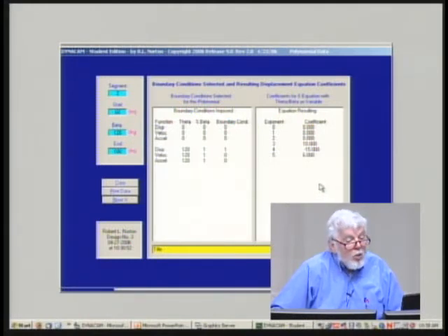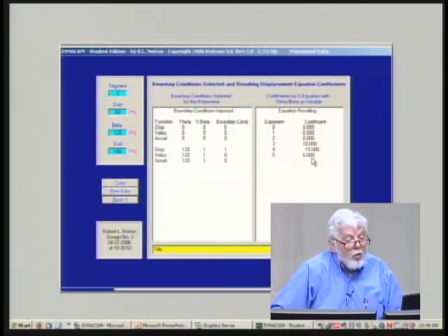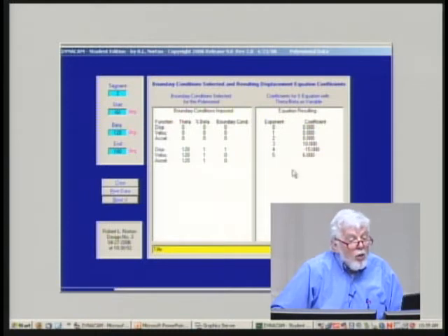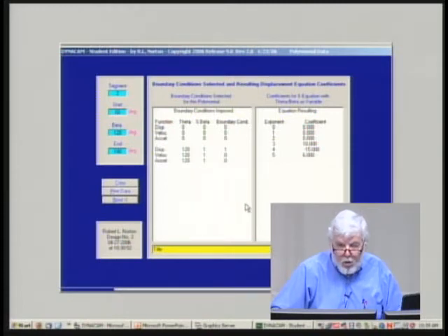not with these beta numbers necessarily, but with 6 boundary conditions, which gives you what's referred to as the 3, 4, 5 polynomial. It gets its name from the fact that the first 3 coefficients turn out to be zeros, and I'm left with coefficients on the 3rd power, 4th power, and 5th power terms. And you know that your highest power will be 5 because you chose 6 boundary conditions, which gives you 6 terms, or 6th order. The first term is 0th degree, and thus the highest term is 5th degree.